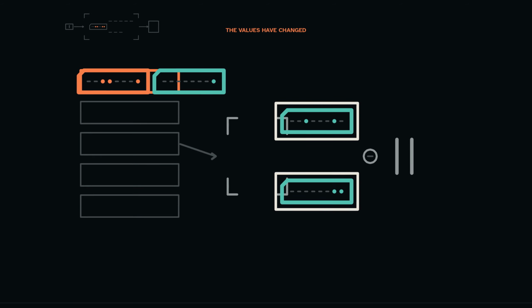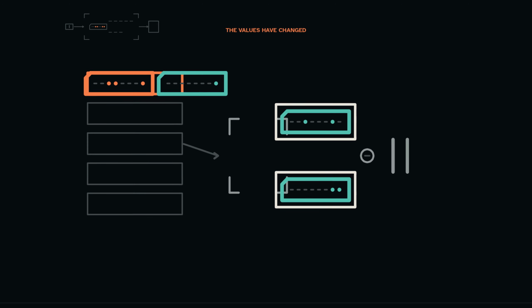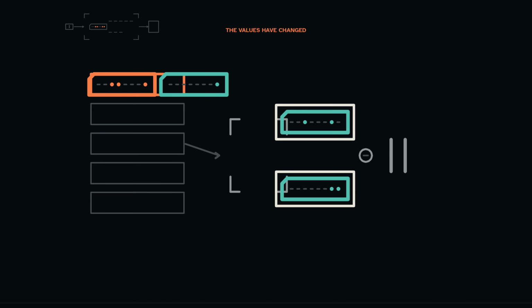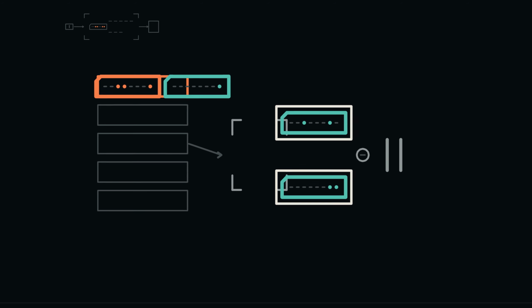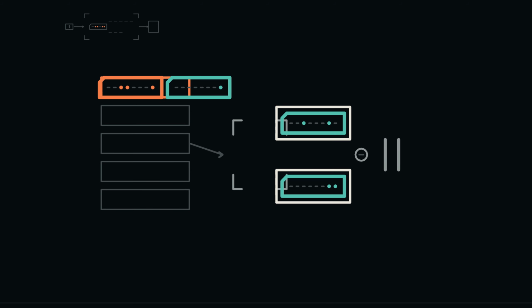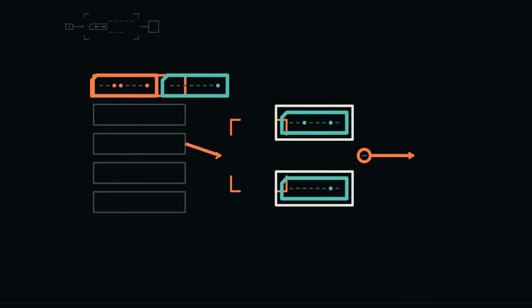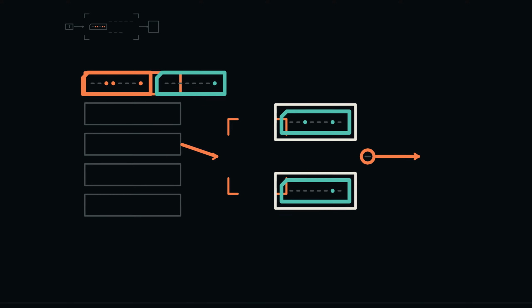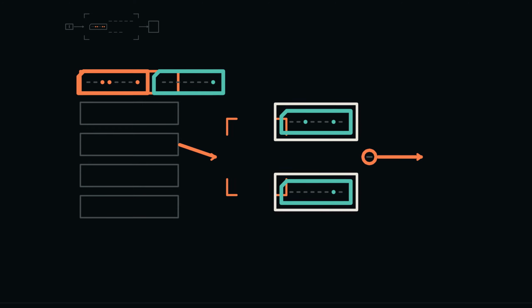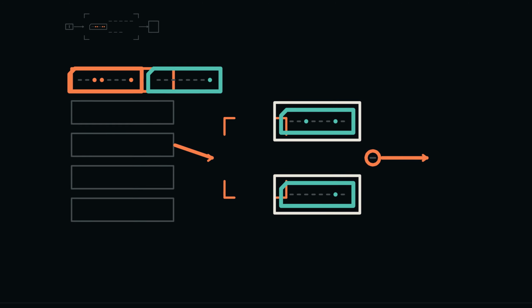Keep the answers separate. Subtraction changes the register and arithmetic flags. Ordinary fall-through was already prepared during fetch. The instruction does not contain a branch, so it cannot replace that next address. 3 minus 1 is 2, so R0 becomes 2. 2 is neither 0 nor negative in 8-bit 2's complement form. The 0 and negative flags are therefore clear. The program counter points to the compare instruction, 2 bytes after the subtraction began.